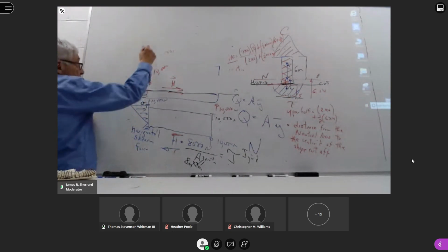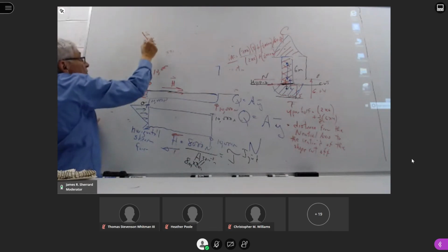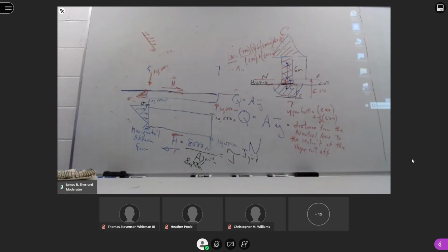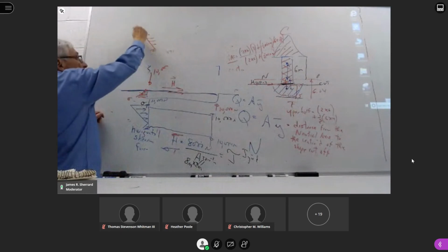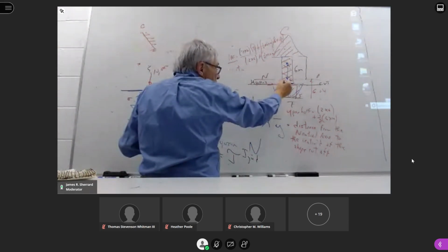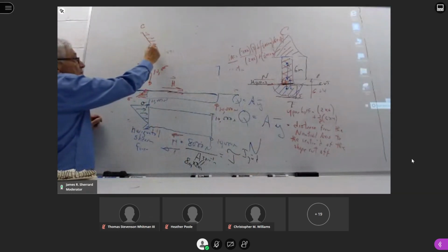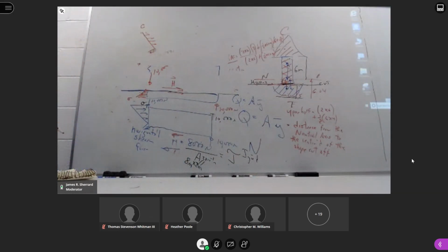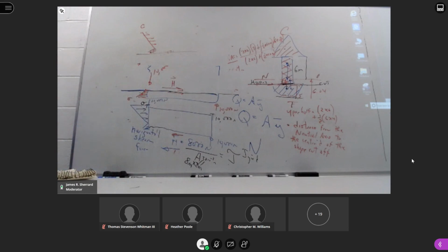But if we go back to the upper part, there was a little section here that was tensile from where we cut it. Because remember, this is the cut line, but this is the neutral axis. So everything above the neutral axis was in compression. Everything below was in tension. But we had a little bit of distance here where we had positive plane stress. And this is our cut line. Okay, I see that now. Thank you.